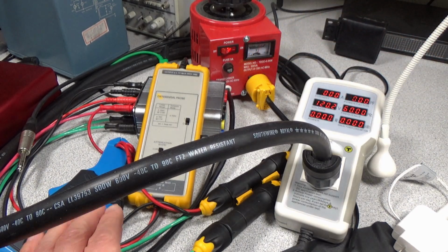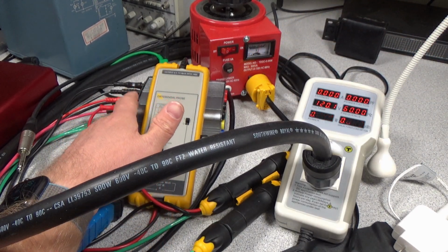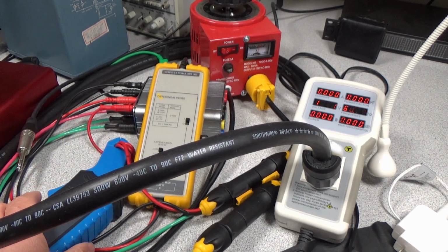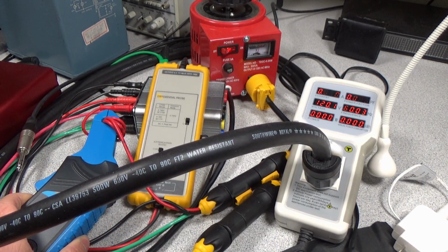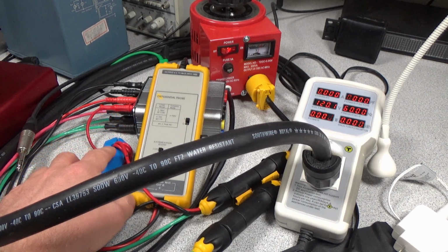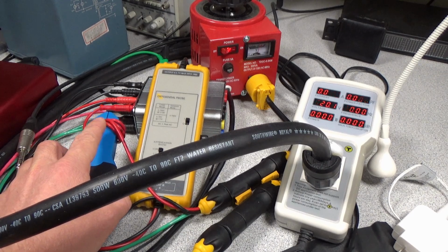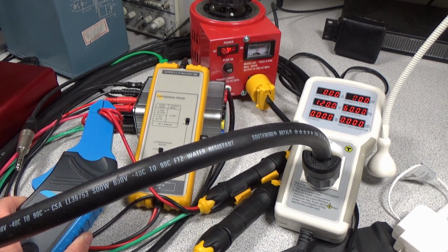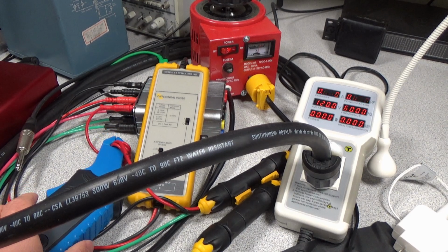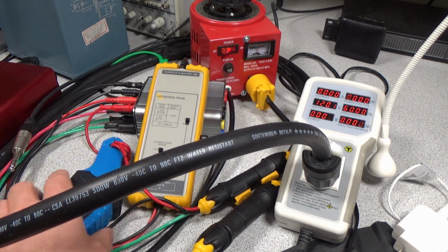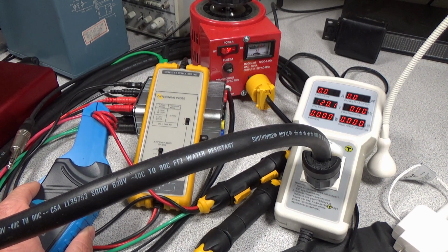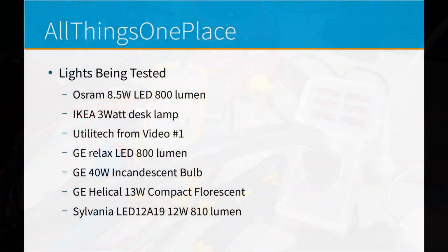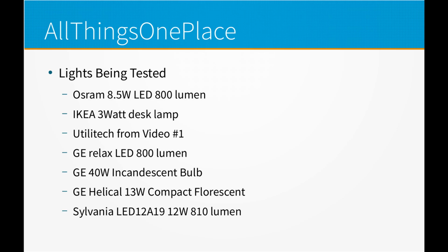And then we also have coming out of this box, going back out to the socket, a current transformer essentially on the output side, and we have 4 windings going around here just to get better signal to noise ratio, because this is a 65 amp sensor, so it's not going to be very sensitive to these LED bulbs where we're only measuring point something amps. So we're using the 4 windings just to get a little bit better of a signal out of that. Just as a note, you have to divide by 4 the values that are going to be on the scope screen.